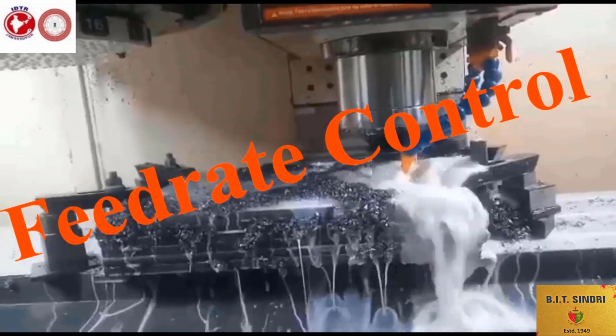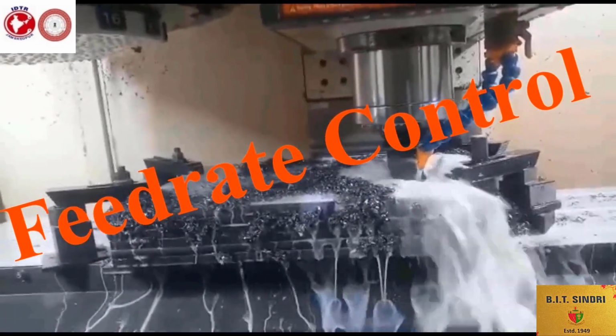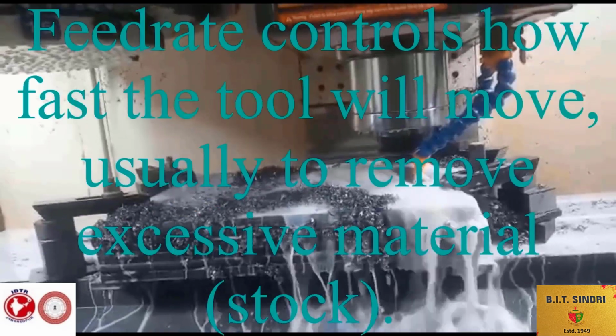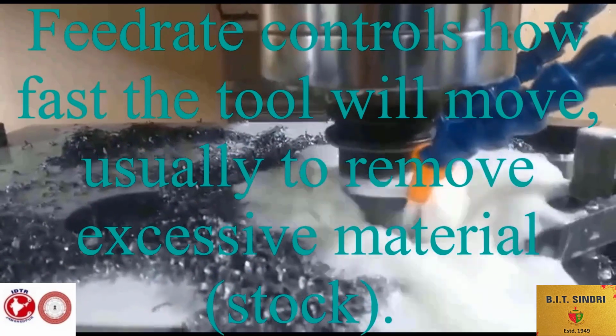The next topic is feedrate control. Feedrate is the closest programming companion to the spindle function. While the spindle function controls the spindle speed and the spindle rotation direction, feedrate controls how fast the tool will move, usually to remove excess material.